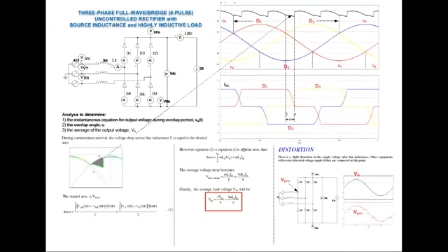All right, so this is the second. We need to consider this area. This is the missing area that we talked about just now. During the commutation interval, the voltage drop across the line is equal to the shaded area. There is a voltage drop across the line inductance, represented by that area here. So we need to find the average of this voltage drop, so that we can subtract it from the average equation we had before without the source inductance, that is, subtract this missing area.